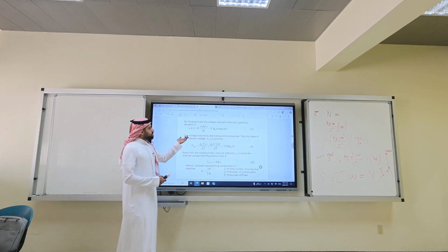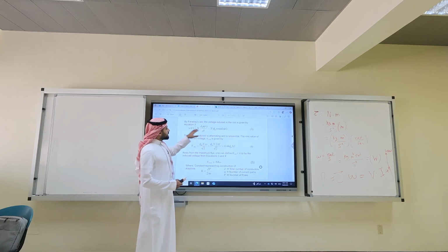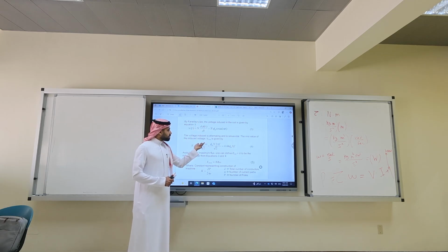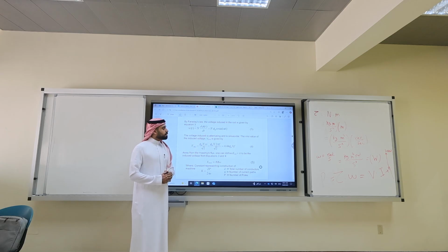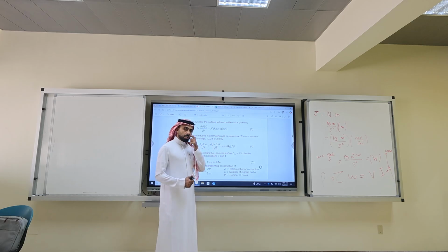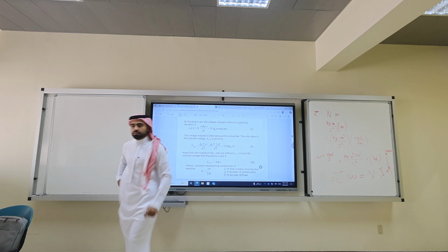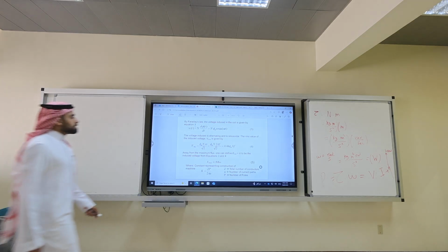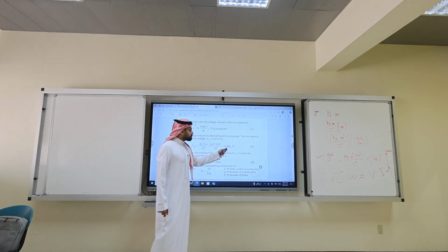Anyway, let's do the voltage. Let's take the RMS. What is the RMS of a sine? Peak over square root of 2. Peak is N phi omega over square root of 2. You agree with me? Yes. Can you do on calculators 2 pi over square root of 2? 4.44. Correct. So this equation, the RMS voltage is 4.44 times flux times N times f.